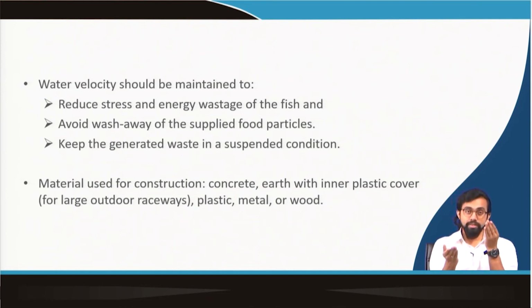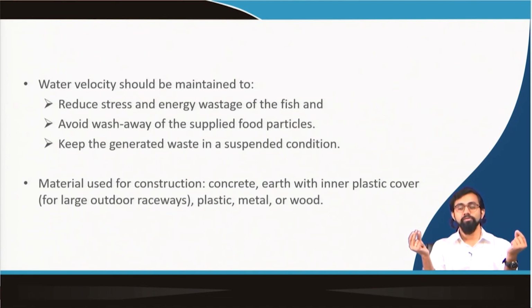So if these three can be managed somehow. Suppose in the case of a long pond with a very high length, you cannot attain the self cleaning velocity, it is very hard. Because to attain it, you have to increase the velocity very high so that the suspended solids will not get enough time to settle on the bottom.